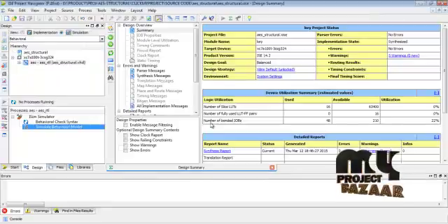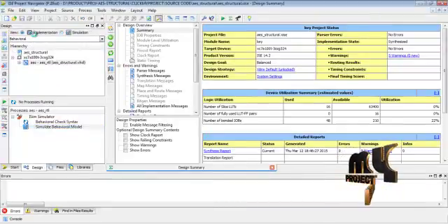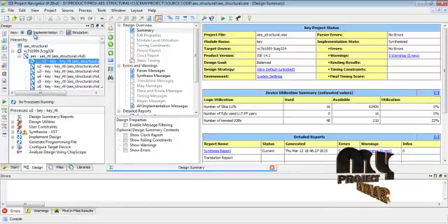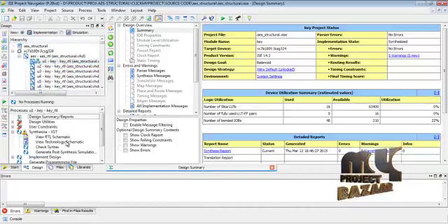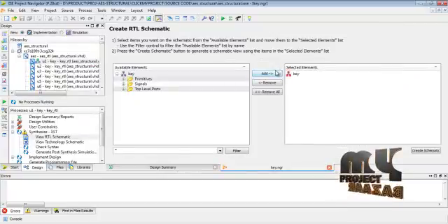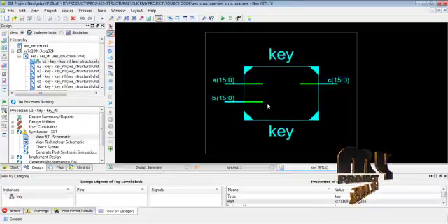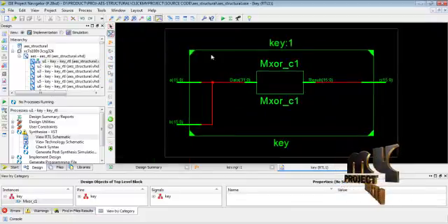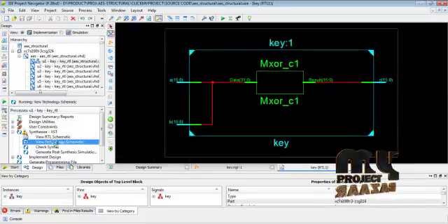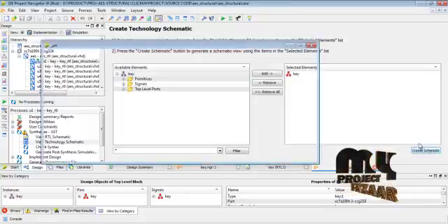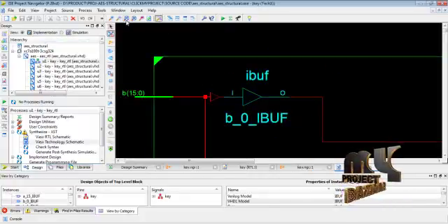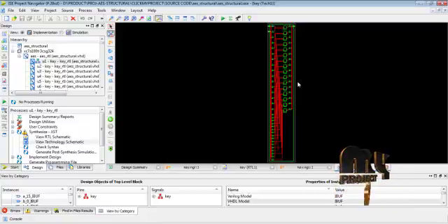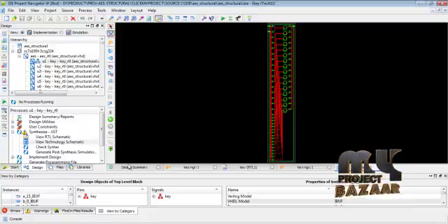Then close the simulation process and select the implementation process. This implementation process describes which logical blocks are placed in our overall architecture function. This is our view RTL schematic diagram. This RTL diagram represents which logical blocks are placed in our overall architecture. Then the technology diagram. The technology diagram is mainly used to describe the logical functions and the lookup table, input output buffers, then the wire connections based on our overall architecture results.